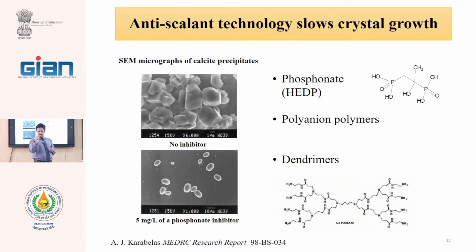After nucleation, the crystal begins to grow over time. But these polymers connect to the small particles and do not allow growth. And when they do not grow, the cross flow velocity of the fluid, after a certain time, can pull them and exit from the RO modules. Therefore, the attachment of the crystal can be reduced with some polymeric anti-scalant, and there are many mechanisms for that.